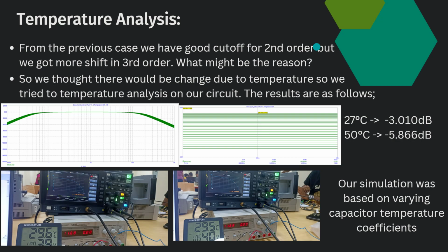And coming to the input and output impedance, we used the software LTspice, where we gave a test source at the input. As we know, the input impedance is calculated by giving a test source and finding the resistance at the input. We gave a test source of 1 volt, then to find the resistance we calculate the ratio of voltage and current, so that we get the input impedance, and the output impedance can be calculated easily using this procedure.